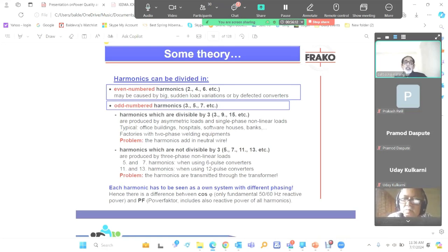So that third harmonic is a zero sequence harmonic. It flows through the neutral. So the neutral is overloaded. What we do, in the IT sector particularly, is use 5-core cables because the neutral current could be even 2 times the phase current. So if the normal half-core neutral is there, it will burn out and there could be accidents and fires and all. Hazards are there. So for installations where the single phase load concentration is more, we use 5-core cables.